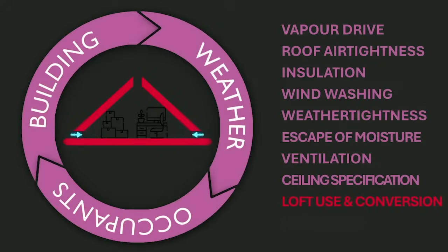If insulation levels are increased as part of energy performance-related upgrade work, this can also block the ventilation openings at the eaves, or if it stops short of the wall insulation, lead to a cold bridge at the wall-roof junction. Either way, this can result in elevated condensation risk and attendant moisture problems.